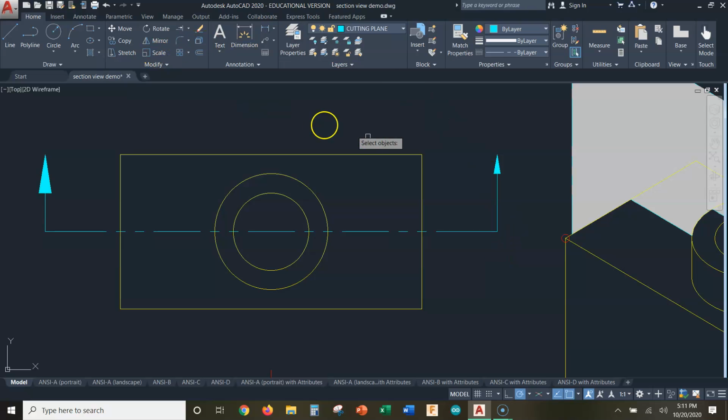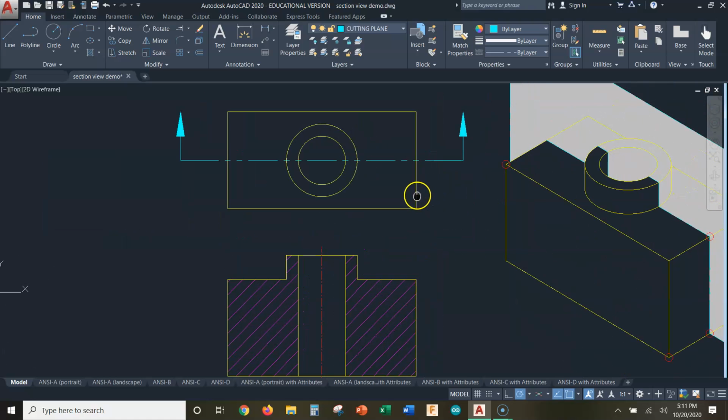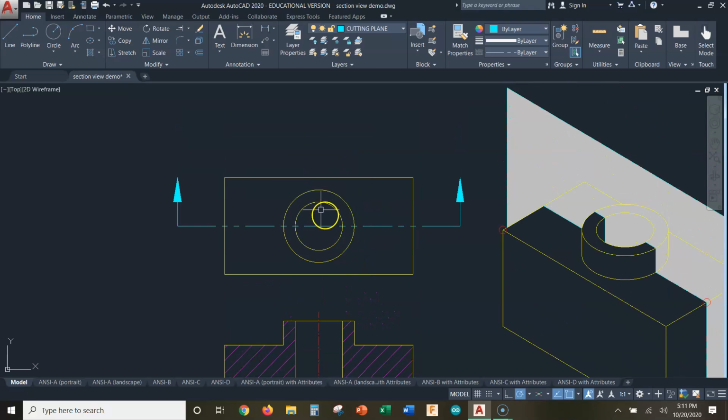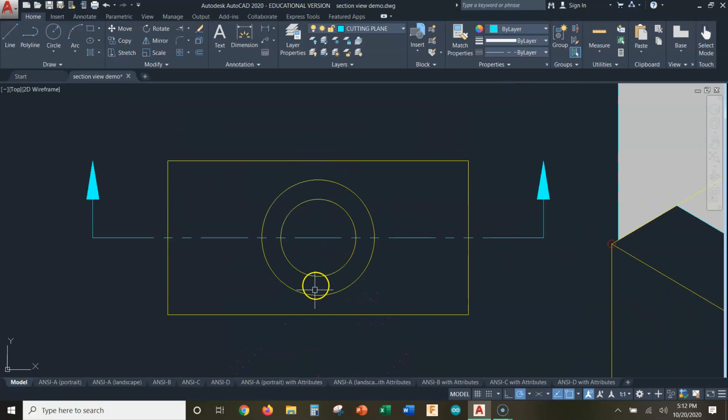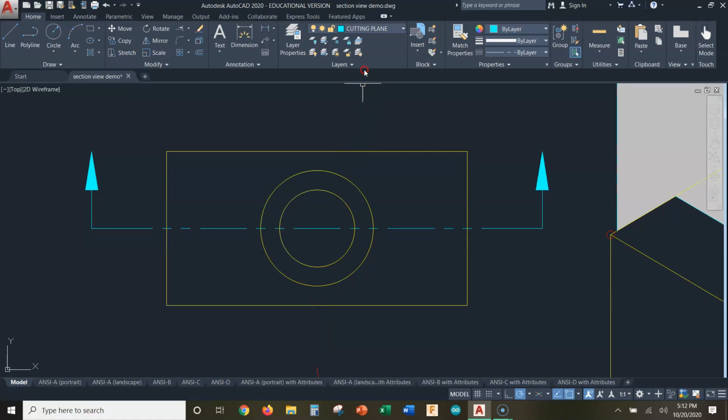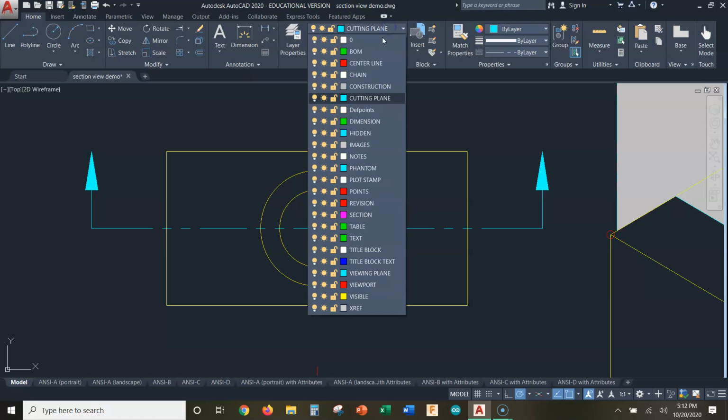All right. Last but not least, I'm going to go to scale. I'm going to window this. I'm going to pick the base point there, and I'm going to scale it by a factor of 2. So there we go. Now, we're not quite done yet. Let me just finish off. We need a center line back in here. We need actually the vertical part of that center line, and that's easy to do. We don't have to use any kind of special center mark command, though you need those commands as well.